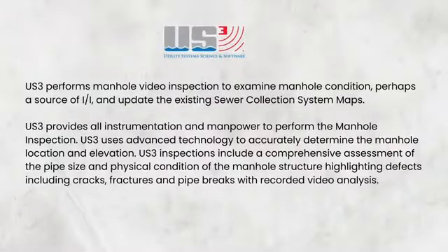We've changed how, once again, we're trying to automate and trying to reduce the costs. And so one of the things that we do today is at every manhole that we think we're going to be monitoring, we send down a 3D camera, or maybe you might put in a LiDAR camera, and we send that down. And we take complete measurements of the whole system. And then what we'll find is what the city thought was their as-built conditions will be substantially different. And substantial can be, they thought that they had a 12-inch channel when they actually had a 10-inch channel.